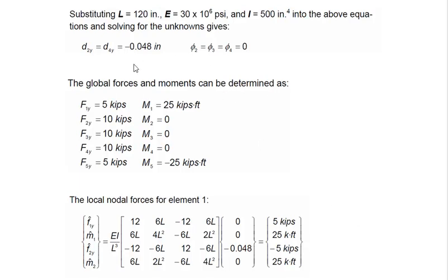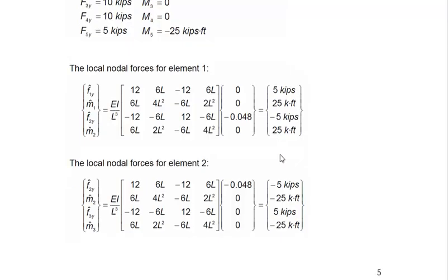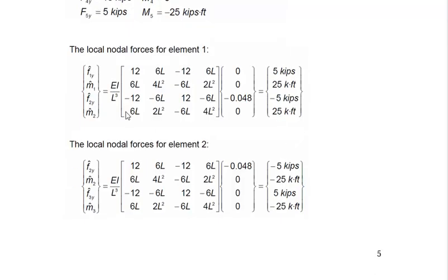So after the displacements, we plug in these values back to the force displacement relationship, and we get the global forces and the movements, right? And after that, if you want to find out the local forces or the nodal forces, then we can consider the force displacement relationship at the local level, right? I'm just quickly going over all of these steps because there is nothing new about these steps.